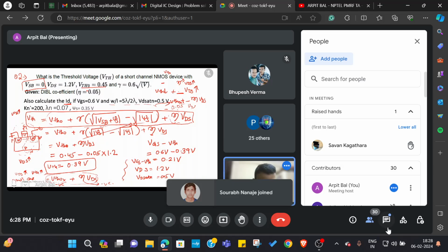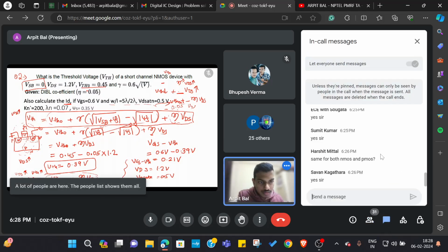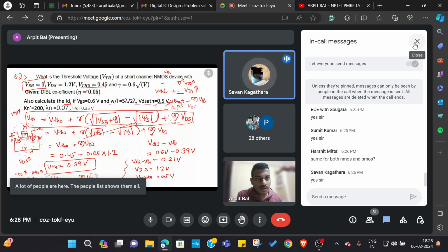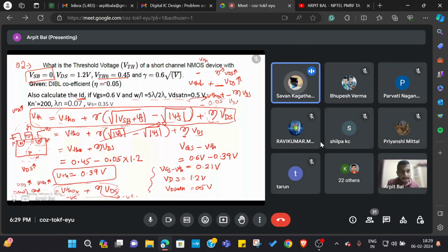Yeah, there's a question someone asked. Sir, in the PMOS case, our VDS will also become negative, no? No, it depends, right? Here I have taken a case in which I have grounded the source and I'm increasing the VD, so it means VDS is increasing.